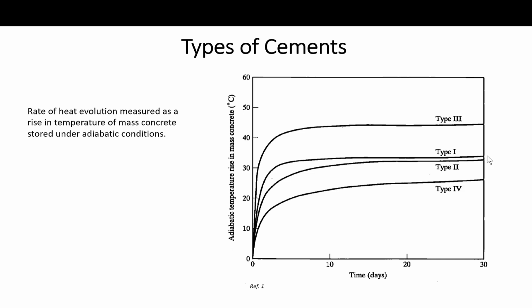If the temperature rise continues after the concrete has hardened, then stresses will develop and cracks will develop due to the thermal differential. So as shown in this graph here, the different types of cements have different temperature rise.